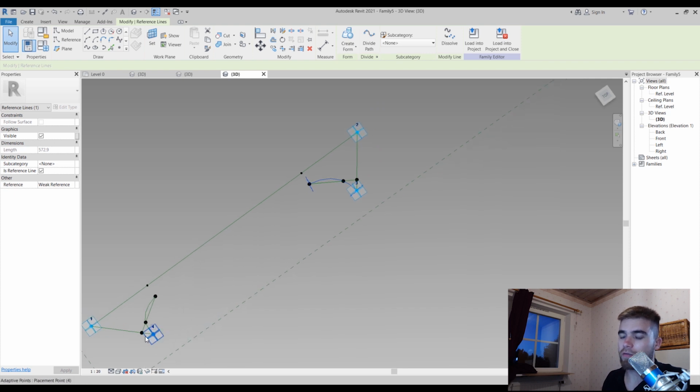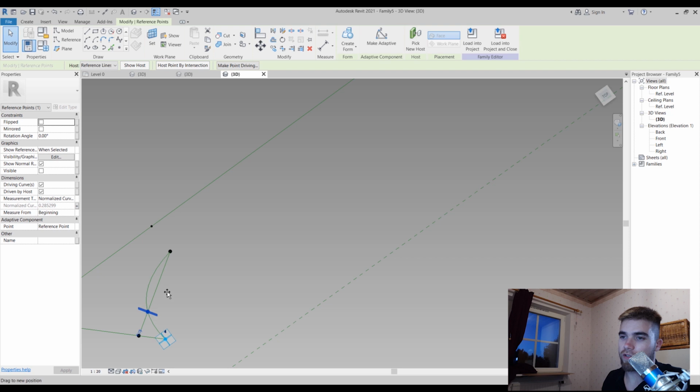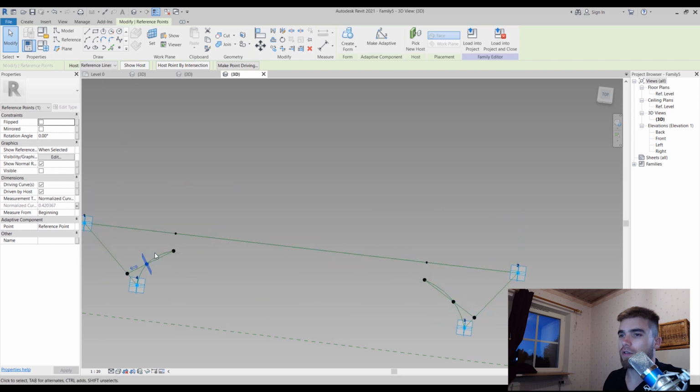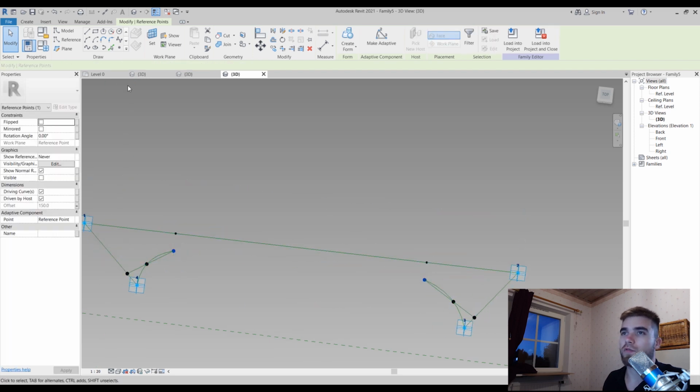And now these 2 parameters that we made, they are changing the character of the spline. So that's why I want them as parameters. And you can see, because they are connected to the same parameter, if I change something here, it changes here as well. This is really important. And I'm also going to create a line between those 2 points.